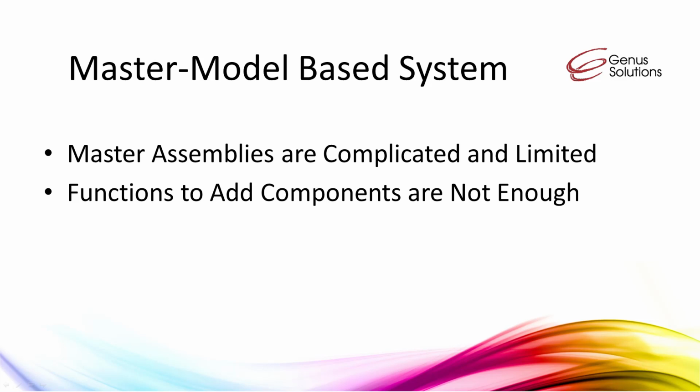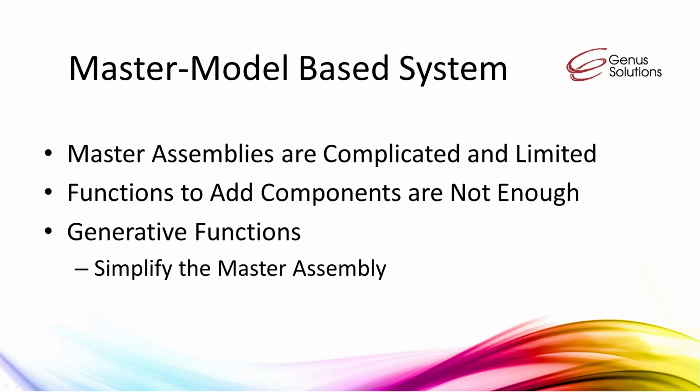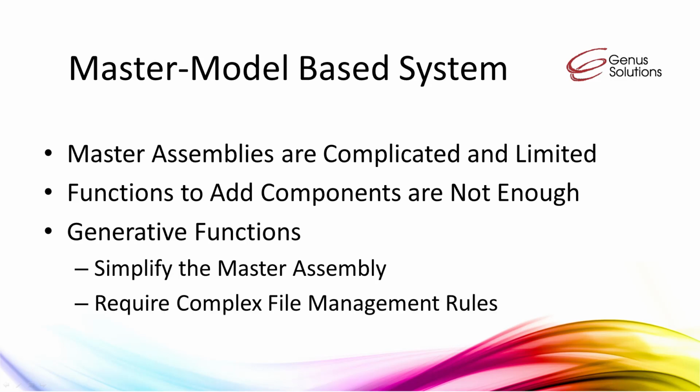But it is also true that simply providing access to these functions in a procedural way does not make a system generative. Generative functions can simplify the master assembly, but at the cost of complex rules used to insert and position elements at the right time in the configuration process. Regardless of the master assembly used, a master model-based configurator also forces you to face the full complexity of file management and embed this knowledge into your configuration rules.